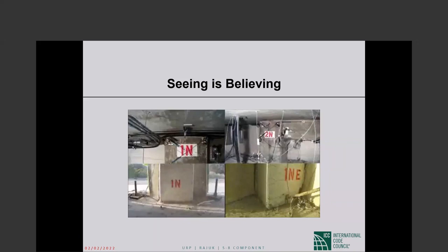If your seismic design category is D, then a flat plate column frame that does not have column line beams cannot be part of the seismic force resisting system, period. The only way you can construct a flat plate column frame for a design category D building is by combining it with 100% seismic force resisting shear walls.